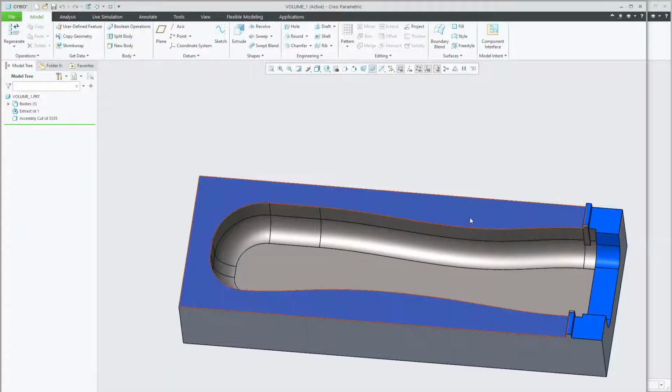But we're going to machine very shallow little channels into this surface just to allow those air pockets to exit through those channels. Hopefully the material won't be able to get down those channels, or if it does, it will be a very fine, very thin skirt of material that can be easily broken away when the molding's complete.